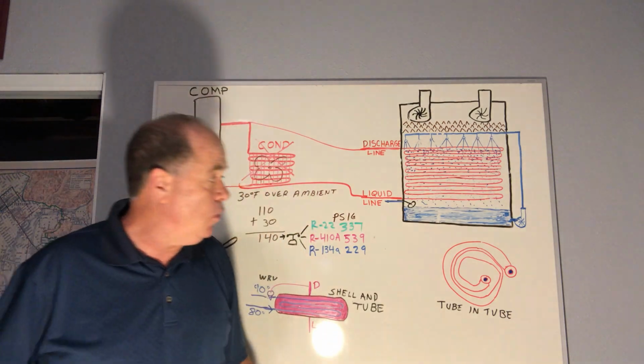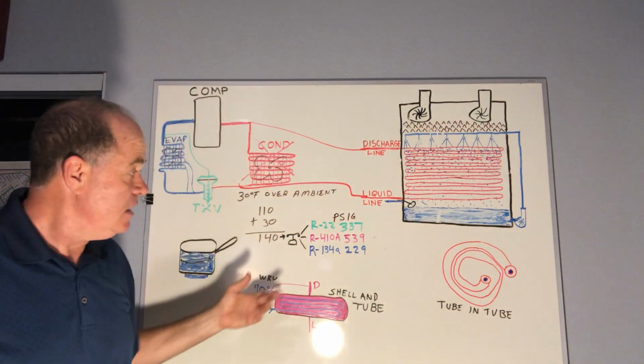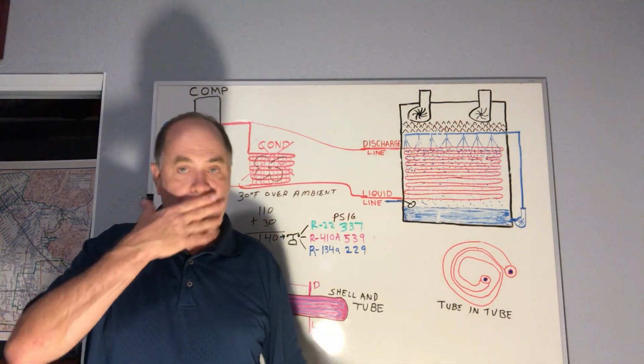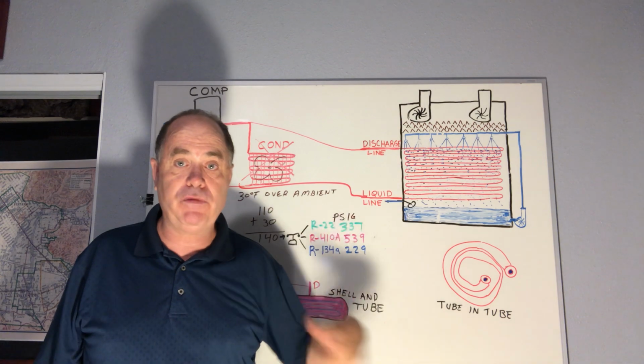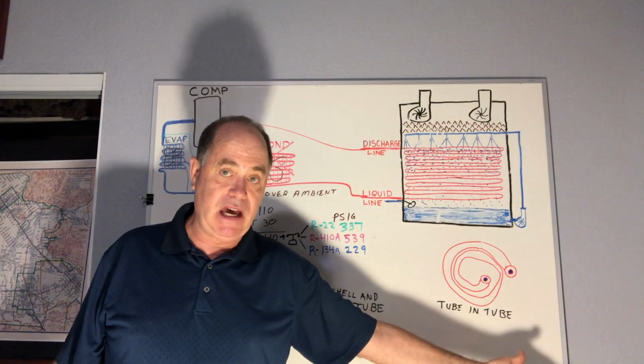So that we're not just having water going through the tower at one time, or water-cooled condenser, and that's it, dumping it down the drain. We recirculate that water and use it over and over, but the mineral content builds up, and then we have to get rid of some of that.